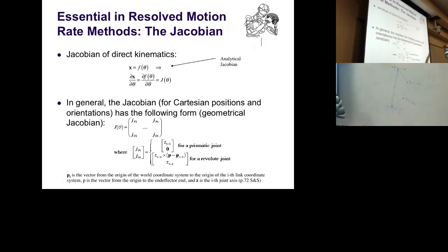But essentially what you're getting is that having this convention, this z, which is a unit vector, rotation axis or joint axis, and that difference from this joint to the end effector allows you with a simple cross product to determine its line of action. And this turns out to be exactly the column in the Jacobian which you need for this degree of freedom. Column, sorry. Let's make this clear.